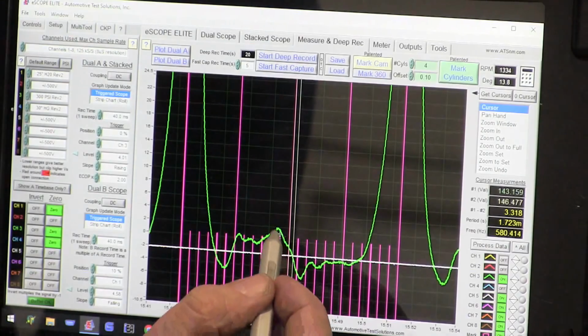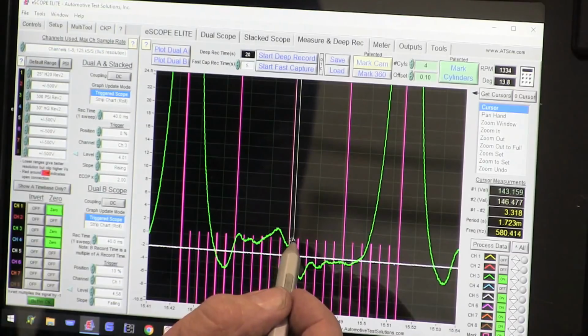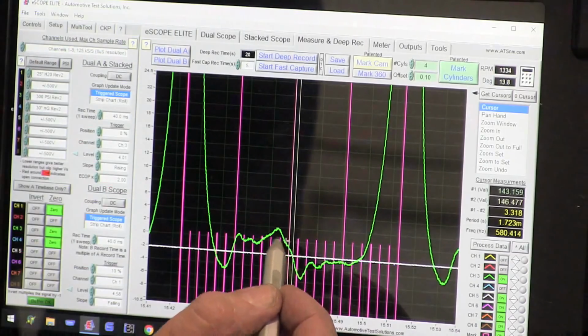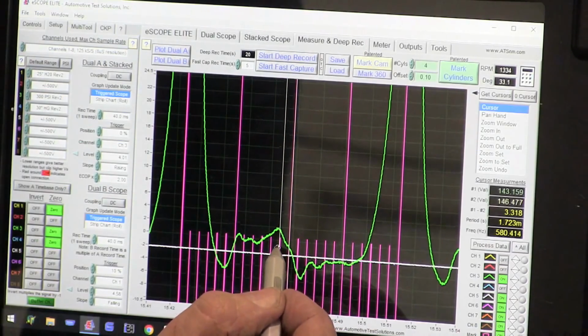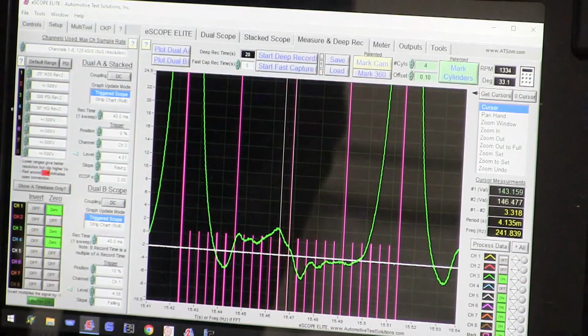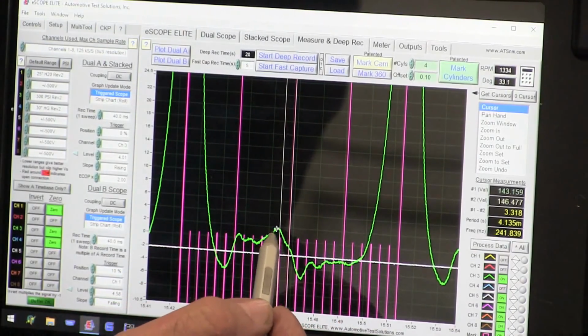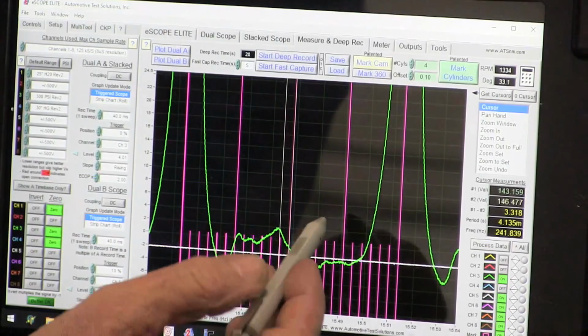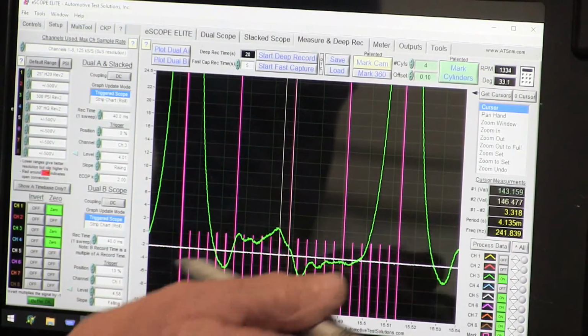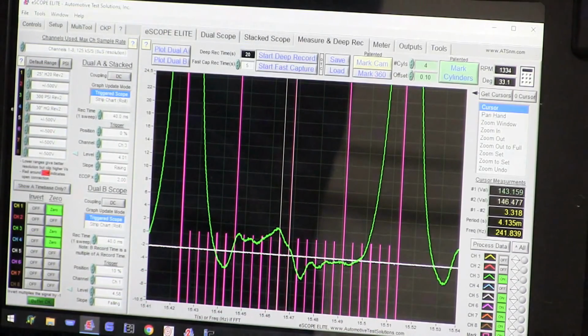So roughly that drop right here should be dropping right here. Now that drop is happening way too soon because it's over here. It's not after, it's way before. So that clearly, with both sides of the intake showing off, the intake cam would clearly show to be advanced, and it's about 40 degrees advanced.